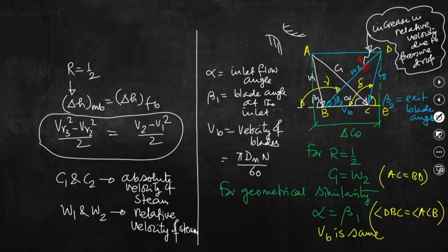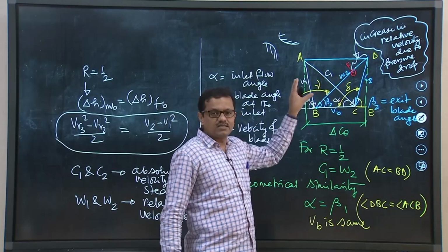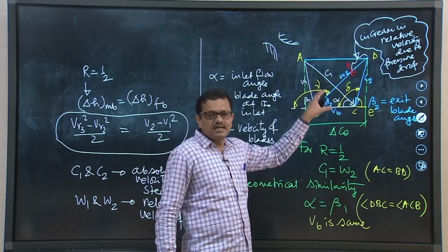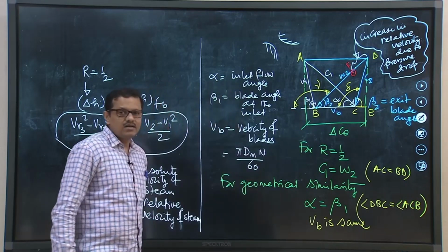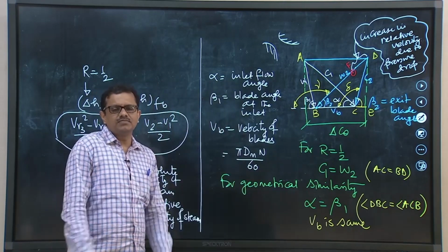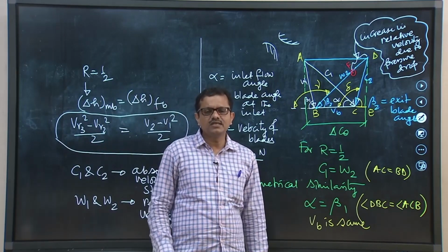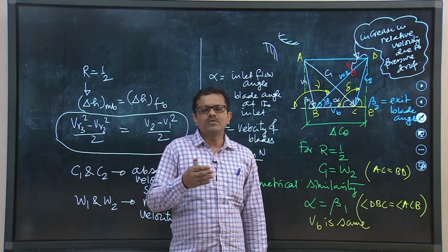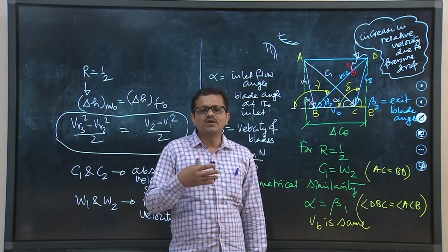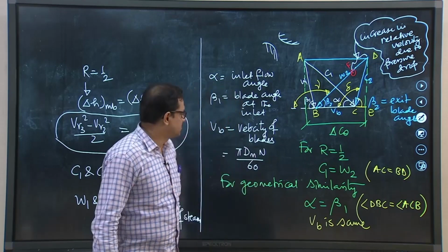So, there is no change in axial velocity. Basically C A 1 equal to C A 2, that we can see from this diagram. Hence, delta C A, that is C A 1 minus C A 2, the difference between these two velocity components, is 0. So there is no axial thrust, but as I said, a small amount of axial thrust would be there, and it is because of the change in pressure or pressure drop when steam is passing through the blades.